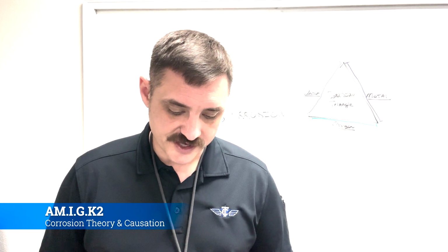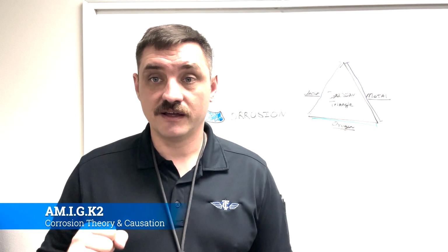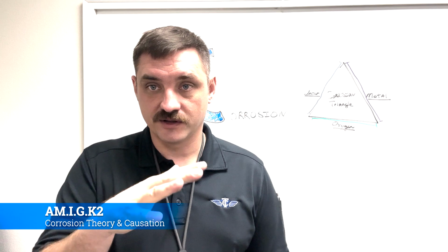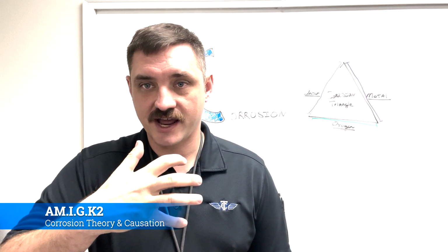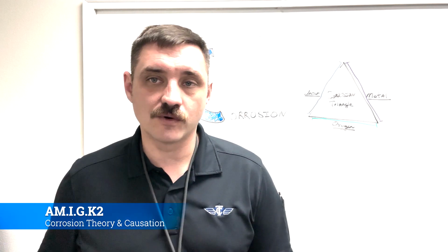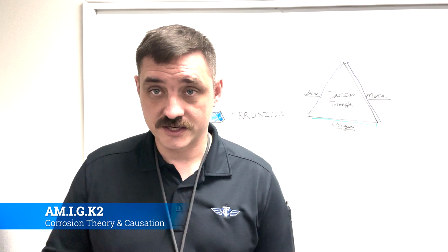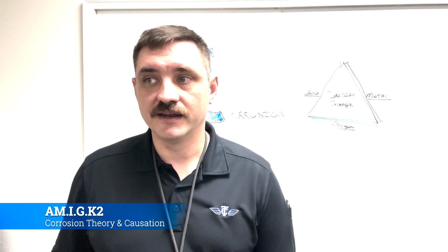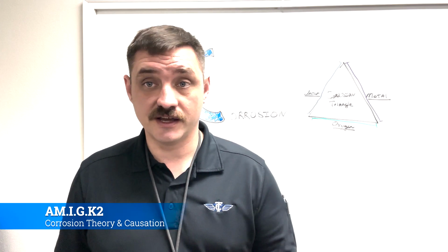Okay, mechanical stress on the corroding metal. All right, so mechanical stress, it stretches things. If you think about my hand as a piece of metal, as it stretches out, you see those gaps that form? Well, oxygen and other material can get in there and start causing corrosion. And that's why you'll do a lot of corrosion inspections on high stress places.